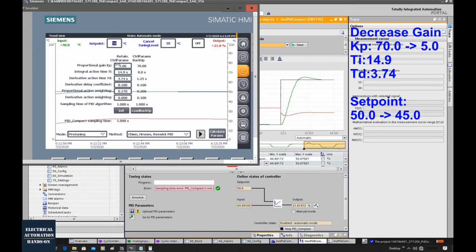So when you try to decrease the overshoot, maybe one way is to increase the gain of your process system. But keep in mind, your increase cannot be too high. Otherwise, it will shift to the first scenario, when the gain is too high, the process is really sensitive. So that means the gain must be in a certain range, cannot be too high and cannot be too low. Because too low, it will cause this overshoot, but too high, it will be very sensitive to the noise.